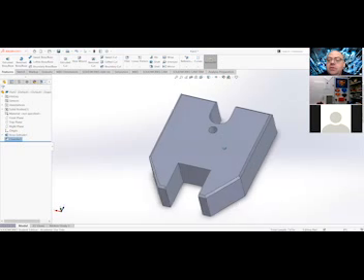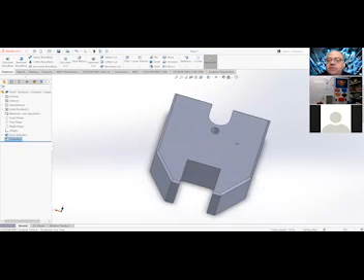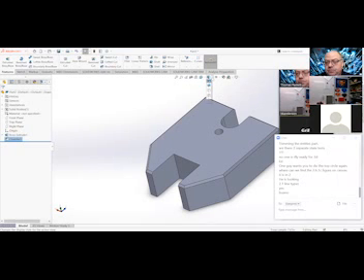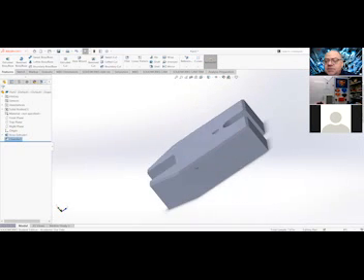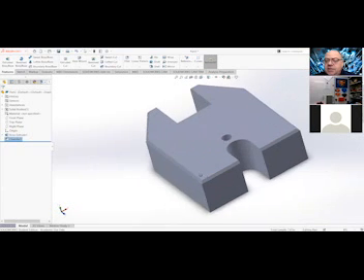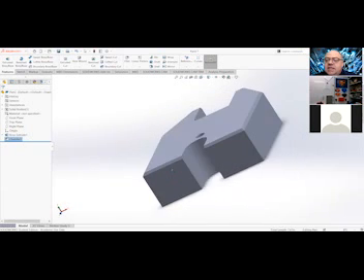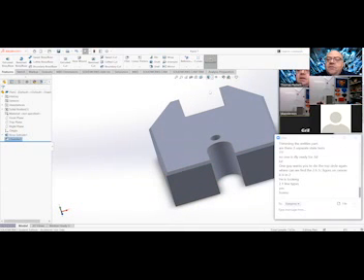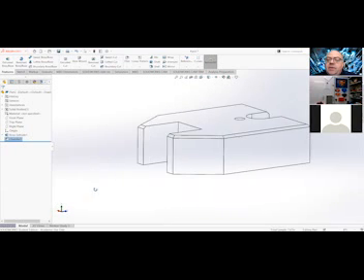Now, while you're looking around here, because hopefully you've got those edges picked, I talked about this next cube, which is your display style. The top one shows edges, so that's where I change direction, shows where things are at. The second one down takes those edges off, just smooths it, so it looks polished. I don't really like that because for me, it's hard to understand what's going on there. The next is a wireframe, so you can see what it'd be like in a textbook.